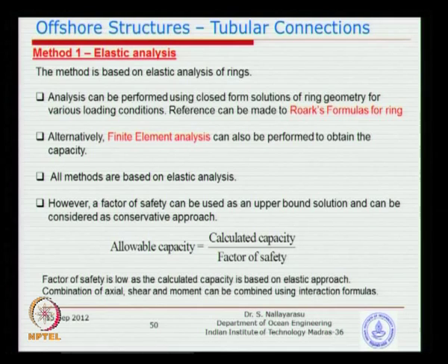If the loads are complicated, then you may be forced to go for finite element analysis. So you could either use the Roark formula if they are very simple cases, but if they are complicated, you could use FE analysis. I think some of you might have already been doing that. So you can see that they can solve any complex problems.